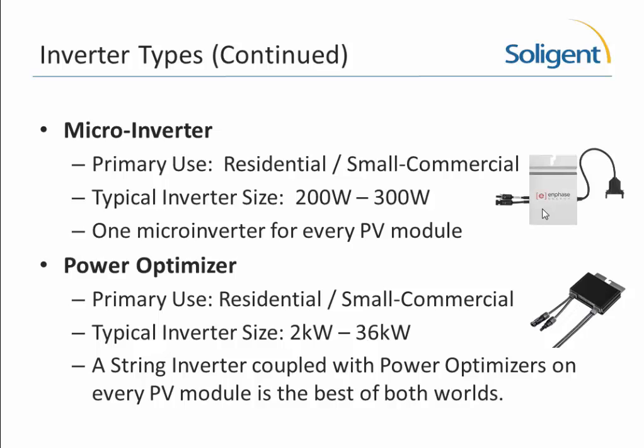So there's certainly advantages to microinverters, particularly in shading situations. You have a lot of trees around, there's chimneys, dormers, whatever. Shading part of the array, one module or part of the array, a microinverter may be the best choice.